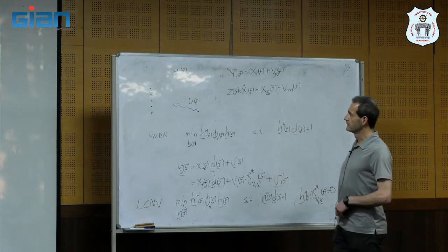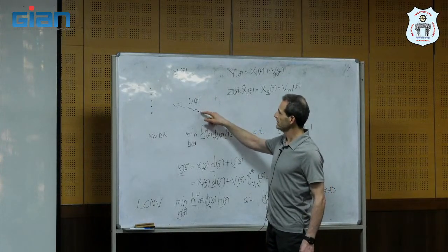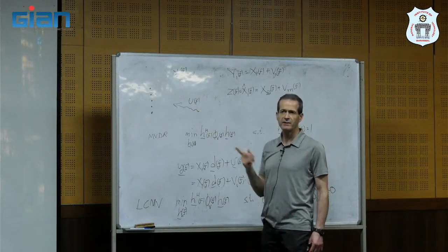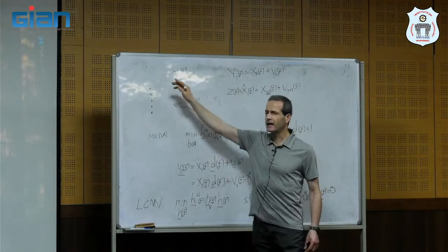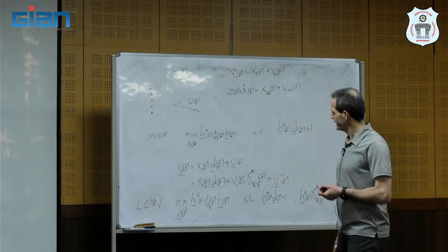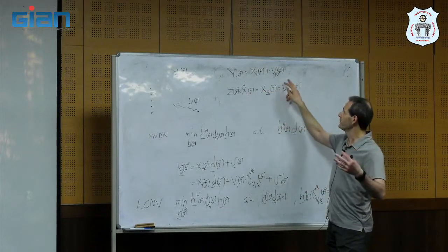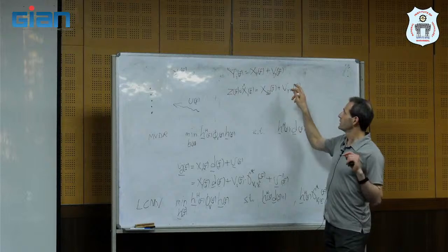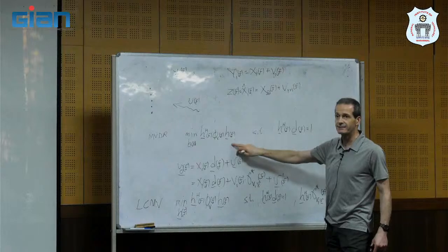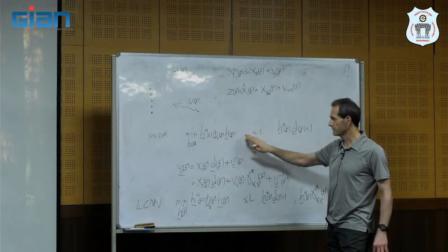Think about it, suppose that we have noise like this, but this noise is very weak, and most of the noise comes from other types of noises. Here with the MVDR, we don't care. We just care about the variance, the power, of the noise, and we minimize it. So we get the maximum amount of narrowband output SNR.